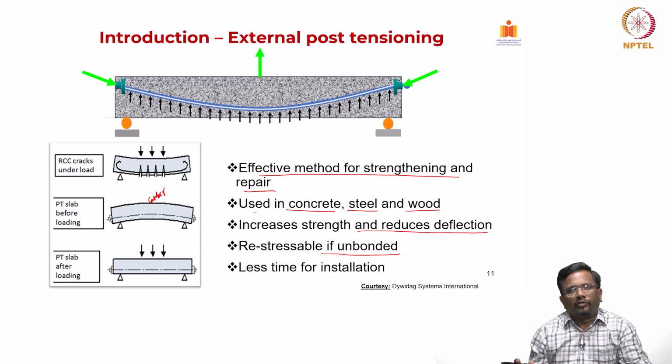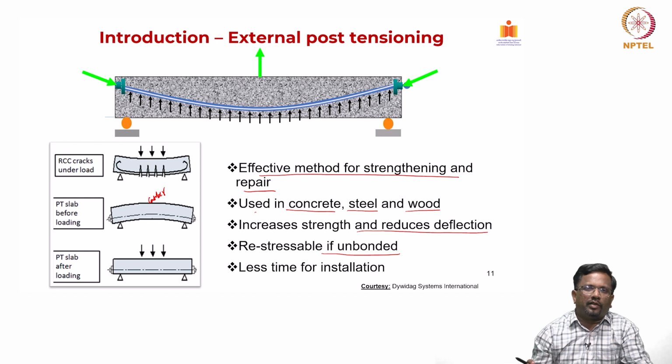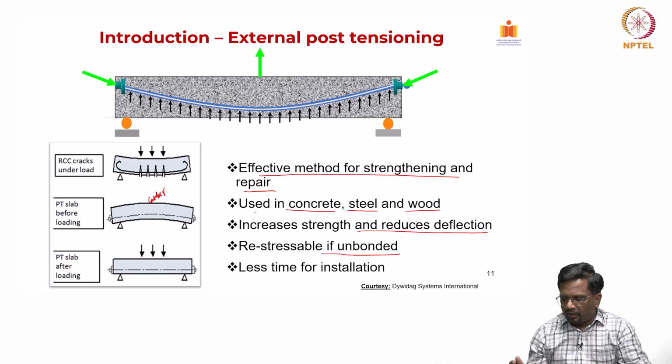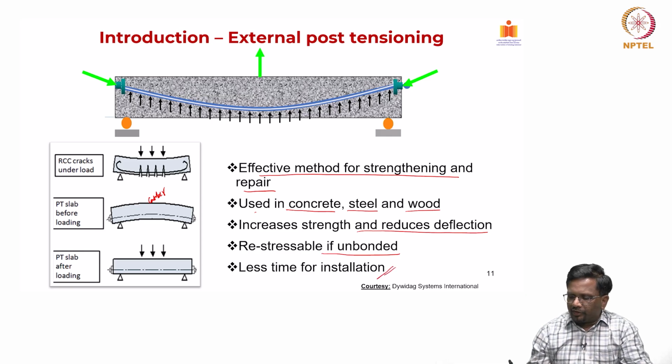And if they are bonded, of course, you cannot re-stress it, but for an unbonded cable I can go ahead and increase the pre-stress at a later point of time as well, right, because they do not have grout inside the cable, and you can actually re-stress it to the level that you want. Less time for installation, because it is quite easy for us to install as well.